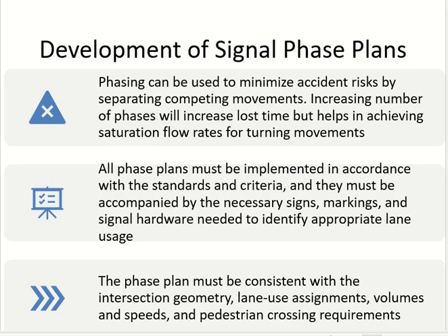Another thing is the phasing plan should be according to the volume and speed. There are 2 important items here. Heavier movements and faster movements are better kept separate from other movements. Especially if you have one heavy movement and one very light movement, or one movement which is very fast and the other movement is very light or very slow. Combining them can be counterproductive.